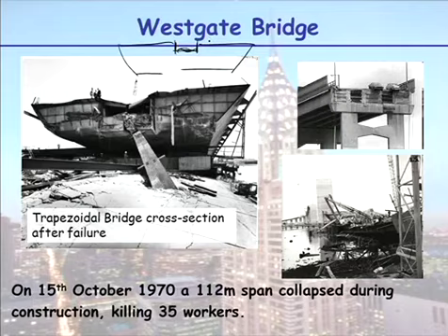So when something starts to buckle, you say, well, let's undo. So they started undoing the bolts. The longitudinal joining was half complete when the orders came through to remove the buckle, which they tried doing by removing the bolts. So as the bolts were removed, the whole thing fell down.